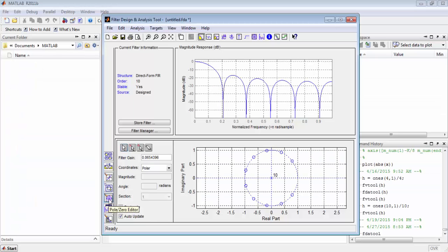Okay, so this is an example of a low pass filter that I designed using what is called the Frequency Design and Analysis tool, or FDA tool. And this is an order 10 low pass filter, and the cutoff frequency for this was set to be about 0.1 omega C. And as you can see that you don't have any, of course, zeros in this region where you are trying to be low pass.